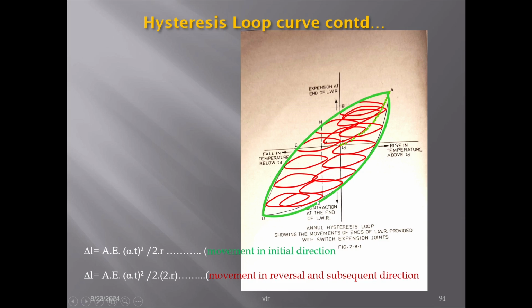So using this only, we are calculating, and finally tabling, the range of gaps. This is not a gap itself, this is only the expansion and contraction for the particular temperature: how much variation, how much expansion, how much contraction can happen at a particular temperature.